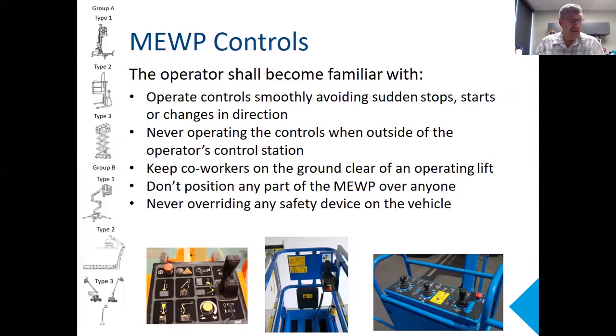Another item to talk about is your MEWP controls. The operator needs to be able to operate the controls smoothly, avoiding any kind of sudden stops, starts, or changes in direction. It takes a little while to figure that out. You've got to have that touch. Never operate the controls from outside the operator's control station. This is definitely a no-no.